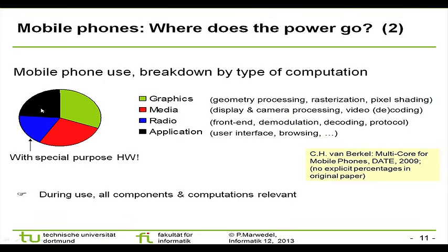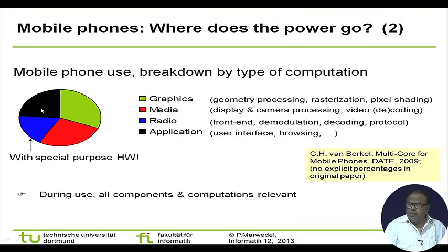Sometimes maybe you are not running audio, or not playing media. Then, according to what we have learned till now, we can put the power off in that processor. Individually I can do that dynamic power management for that processor, which I could not do if it was a monolith, a single processor.